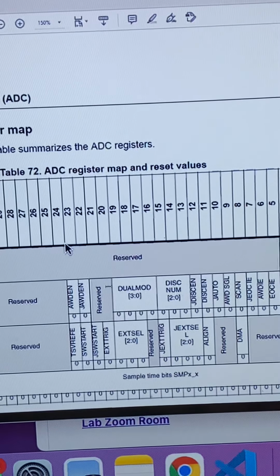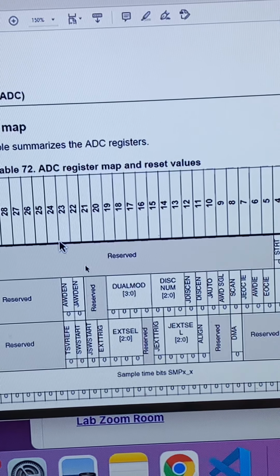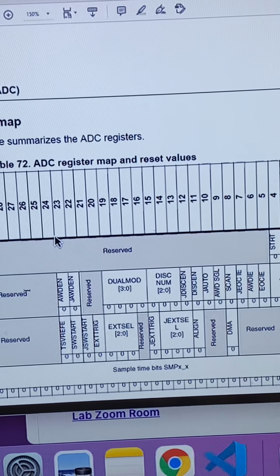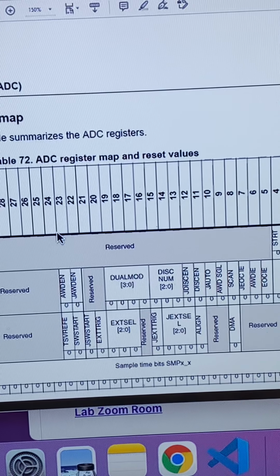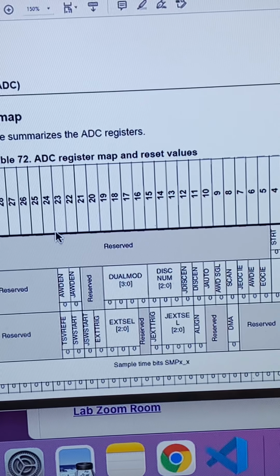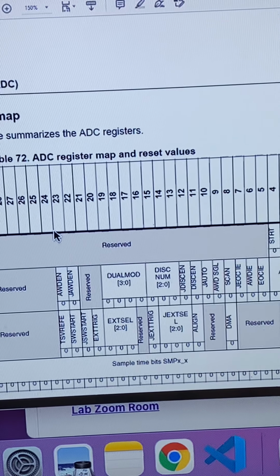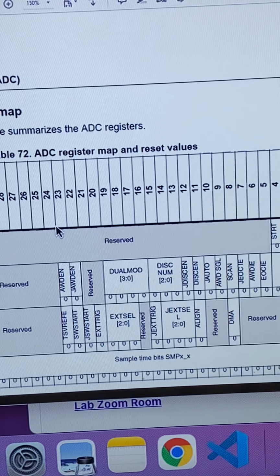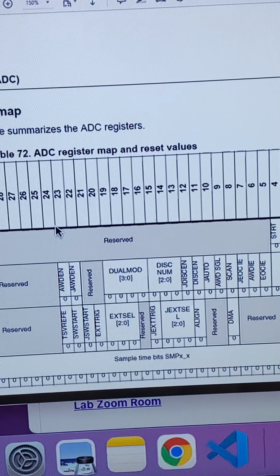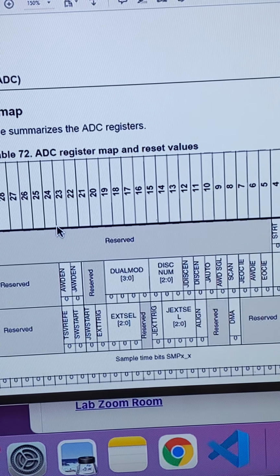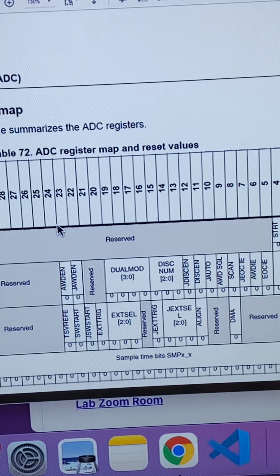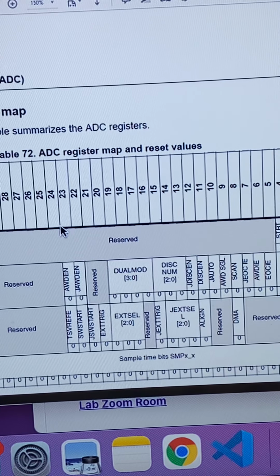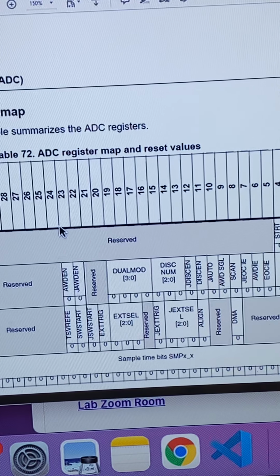When it comes time to use the A to D converter, if you follow that sequence of events from the pre-lab, it says you have to start a conversion. To start a conversion, you simply write this bit again. You never actually make it a 0. You just keep writing 1s to it. You write a 1 to it during initialization, that turns the A to D on. It's just not doing anything. You write a 1 to it again, it starts its conversion sequence. Okay? Now, when it starts its conversion sequence, it needs to know which channel it's converting.